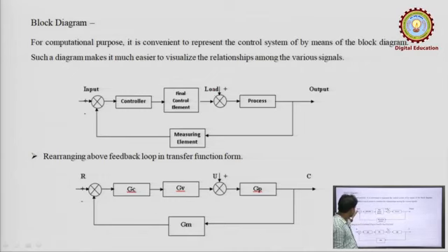That is the set point, and the error occurs here. That is Tm, that is Tr, and the error is Tr minus Tm. The error goes to the controller and is then instructed to the final control element to control the error of the system. That is basically the diagram of the stirred tank heater.